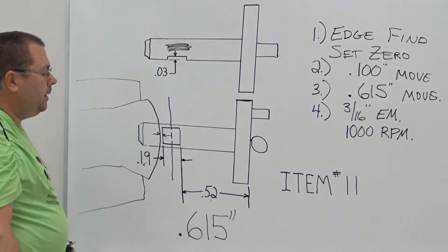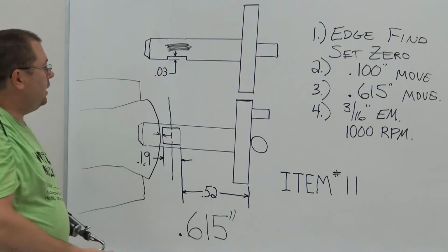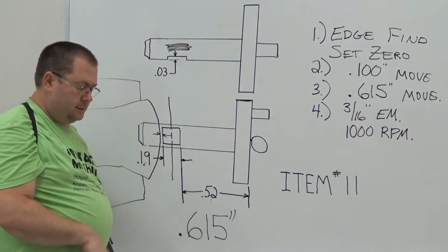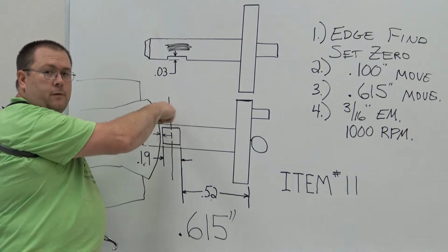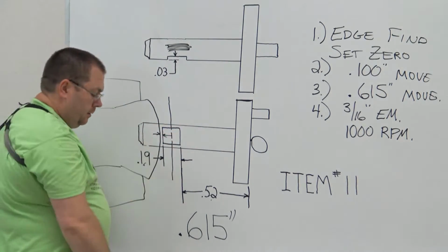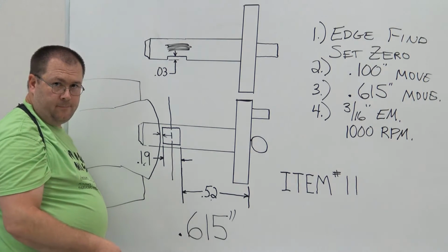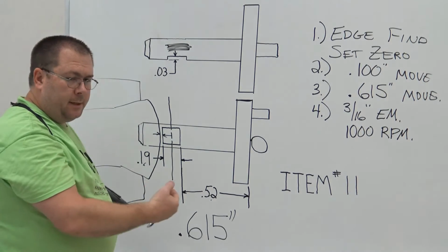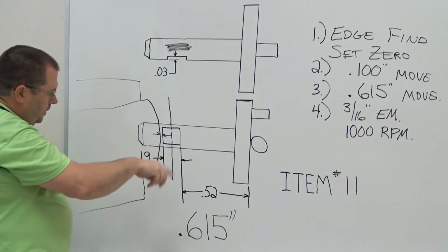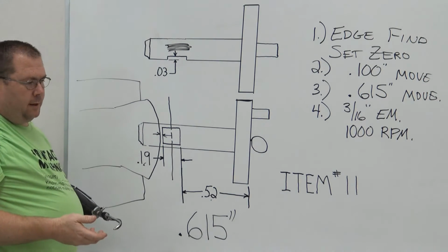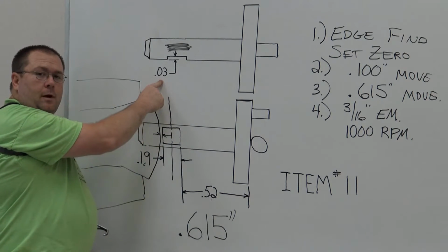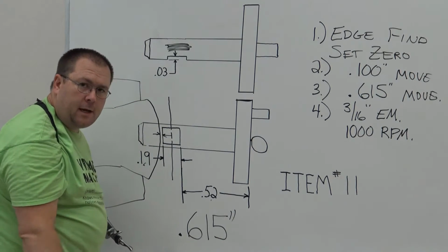Once we set it to 0, because these are pretty stiff machines, you potentially could take all 30 thousandths at one time. But I would prefer you to take it in 2 passes. So we're going to move up. Once the end mill is moving off to the side, we're going to move up 15 thousandths, put some cutting oil on it, take our y-axis and feed across. Don't have to worry about climb or conventional milling because we're going straight through the part. I get equal forces on both sides. The rotation wants to drive it one direction, but I don't have to worry about climb or conventional. Okay? So now we're going to dial it up another 15 thousandths to come to our 30, and we're going to feed back through. Again, make sure you got cutting oil on there.